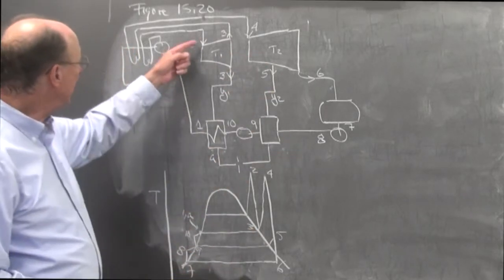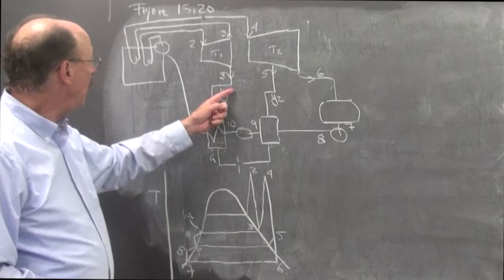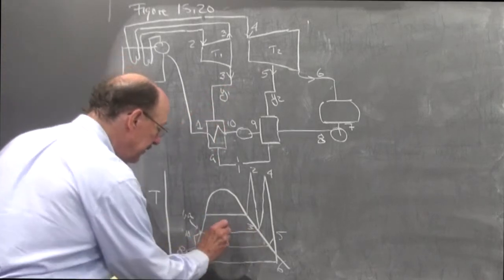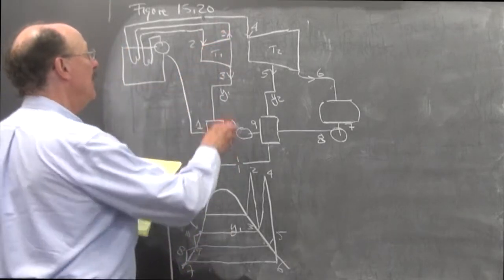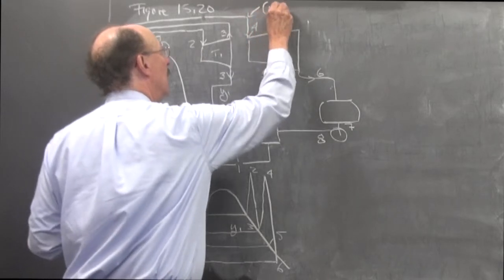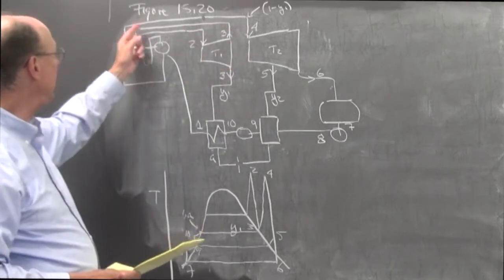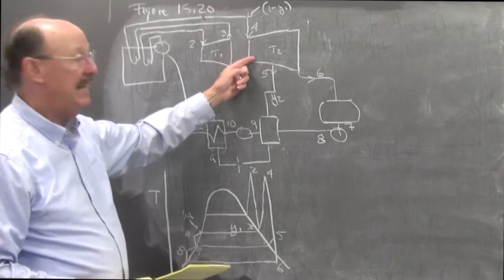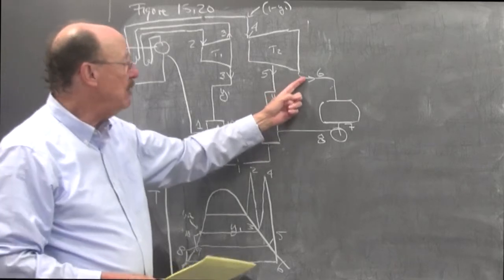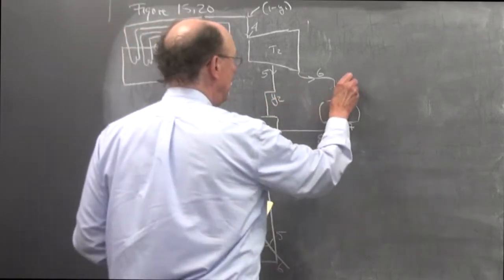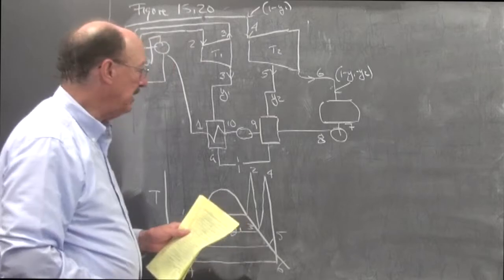If we look here, we have steam coming in at state 2, expanding through the turbine to state 3. Y1 is removed, so Y1 goes over and is condensed. 1 minus Y1 goes back and is reheated, comes back into turbine 2. It expands partway through the turbine and Y2 is removed. It condenses, and 1 minus Y1 minus Y2 expands and leaves the turbine.